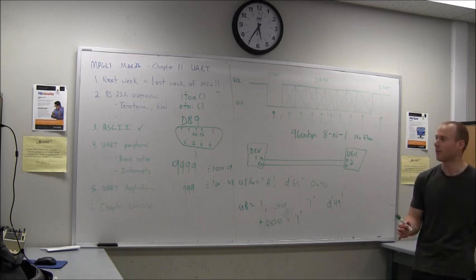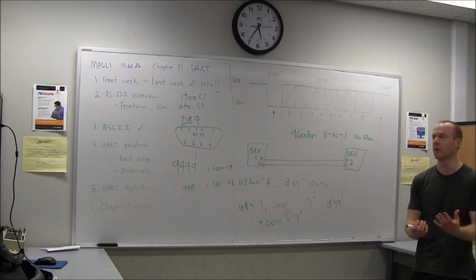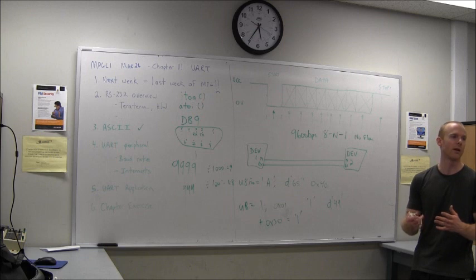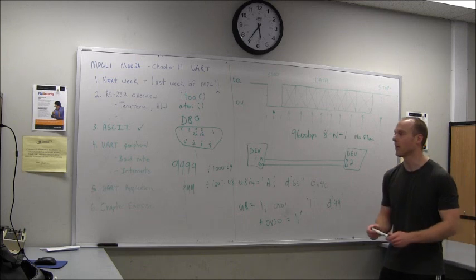As I believe what I've done here, I decided to go for the receive. So whatever bytes come into the microcontroller is interrupt-based, okay, because that makes sense. You never know when those are going to come in, so it makes sense to have them on an interrupt. For transmit, we're just sending them out one character every time we go through our regular 1 millisecond loop. So it's a bit different. You kind of get a glimpse of doing it interrupt-driven and non-interrupt-driven with the way that I wrote the driver.